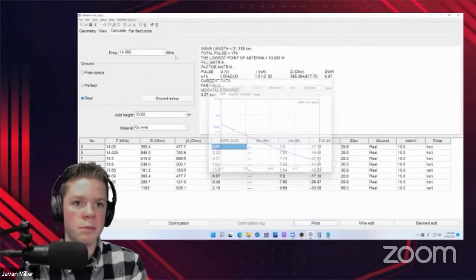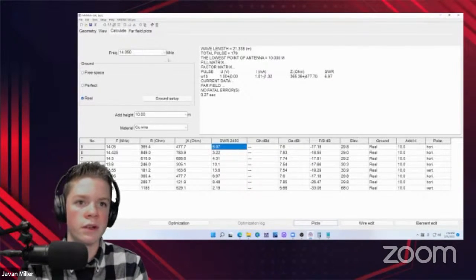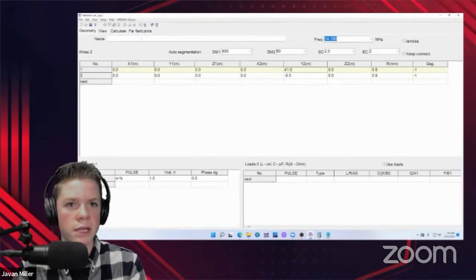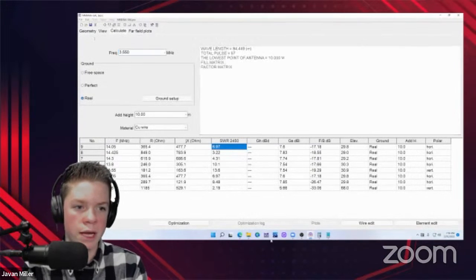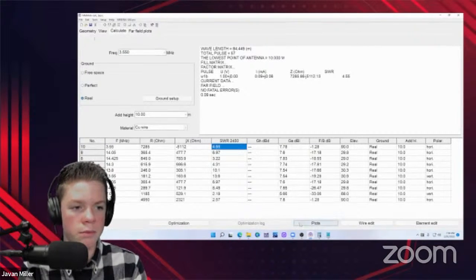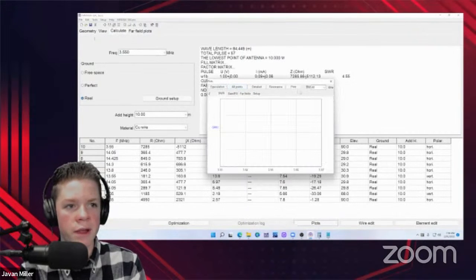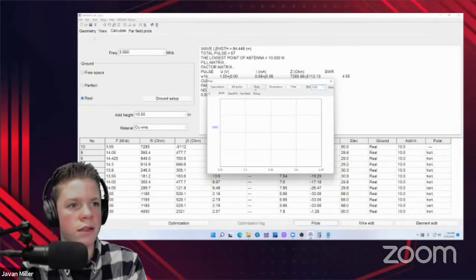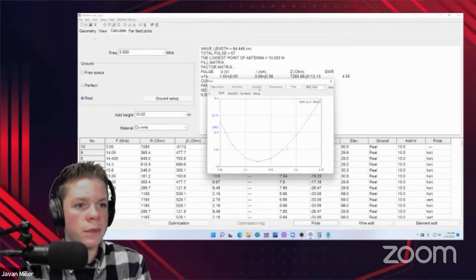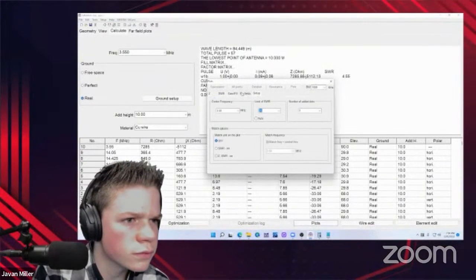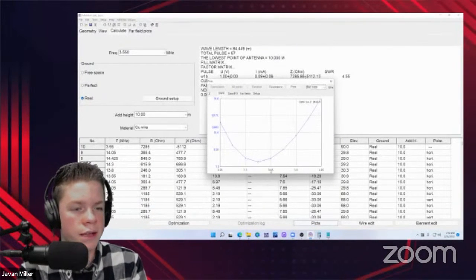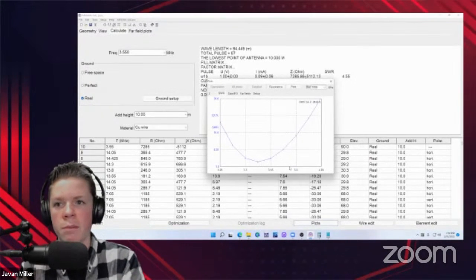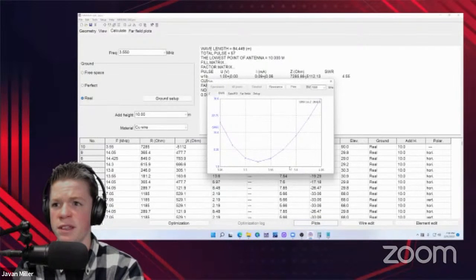So we're going to have to lengthen this a bit to even lower on 80 meters. Let me add another meter of length to 41 meters and see where the resonant point is on 80 now. So let's go back over here to the SWR tab and run another scan to see where the dip is on 80. All right, so you can see here that the dip is now much lower, around 3.4 megahertz on 80 meters. So we definitely are having a problem here.